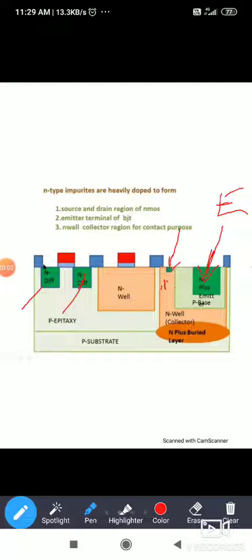Now the n diffusion is over; here p diffusion for PMOS. Here p diffusion for the source and drain region of NMOS, and the second emitter terminal of BJT. Here in the BJT, this is the emitter terminal. Next, the N-well collector region for contact purpose, where you will use a small amount of doping.